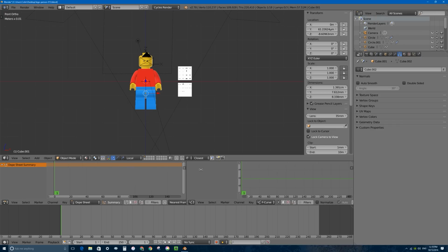I'm going to make it a little bit narrower though, and the sidebar of it a little bit narrower as well. To get started on animation, I'm going to turn on my red record button down here that will automatically insert keyframes whenever I move or rotate or scale an object.